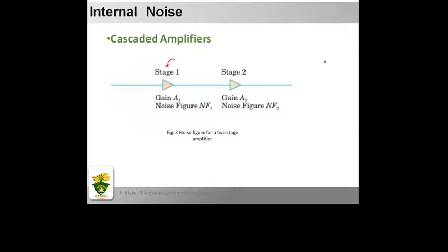While the first stage is the most important noise contributor, the other stages cannot be neglected. It is possible to derive an equation that relates the total noise figure to the gain and noise figure of each stage. In the following discussion, the power gains and noise figures are expressed as ratios, not in decibels. Just take note of that in our following derivation.